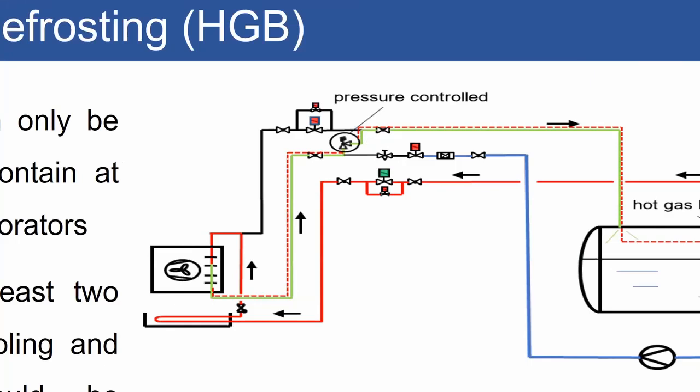Okay, Kamasa, here is the dotted line you are seeing, red color. That liquid is flowing and it is coming to the vapor line. You can see here, top. And then it is going to a receiver. So it is not coming to the blue color line going to the pump. So defrosting is from the outlet of the evaporator.